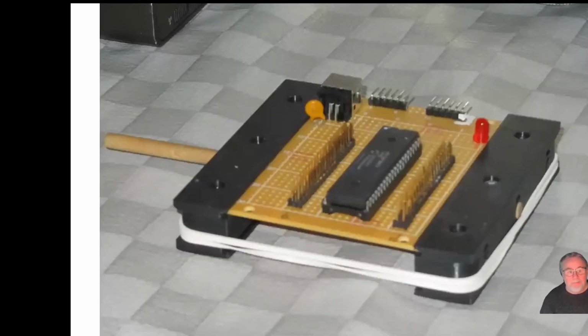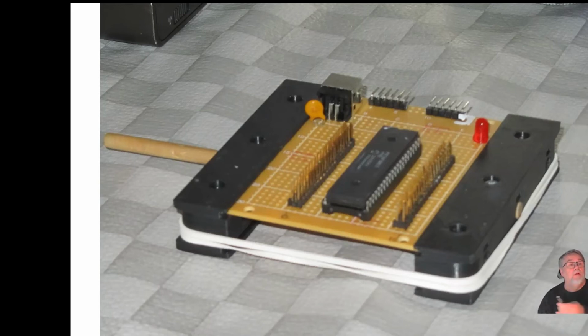This is one of my development boards for developing PIC circuits on. And how I supply it is, rather than put in a power supply or use a wall wart or any of that good stuff, I'm invariably developing these things in front of a computer, a laptop or a grandpa box or whatever. So what I do is I run an ordinary USB cable from the grandpa box and plug it into the board. And the 5 volts from the USB will supply the board.